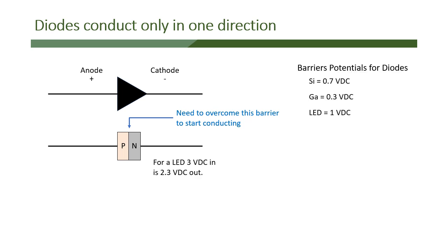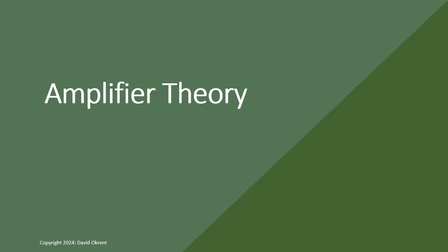And so, as I just said, listed here on the screen, and just to finish up that, diodes, because they conduct only one direction, as we talked about earlier in session 2A, if we put an AC current on the left side, the P side of that diode, it's not going to conduct the negative side. So therefore, we're going to get pulsating DC out of the other side. It's only going to turn on when it's positive. It's going to ignore the negative side of the sine wave.